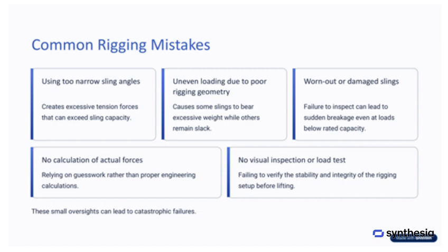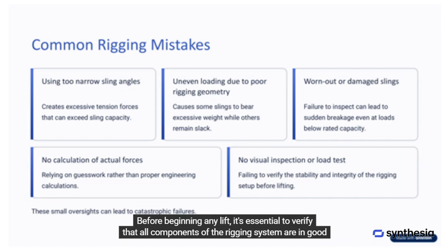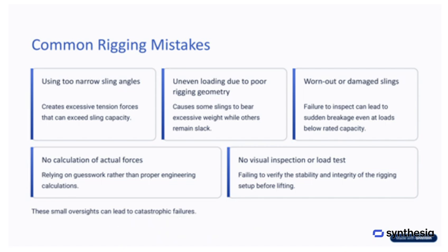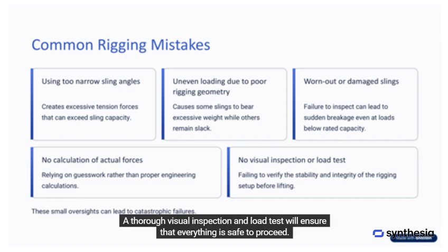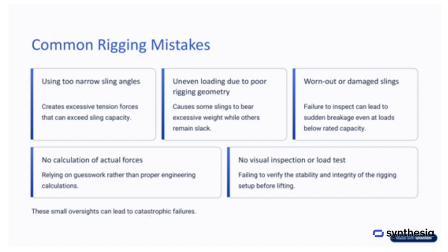No visual inspection or load test before lifting. Before beginning any lift, it's essential to verify that all components of the rigging system are in good condition. A thorough visual inspection and load test will ensure that everything is safe to proceed.